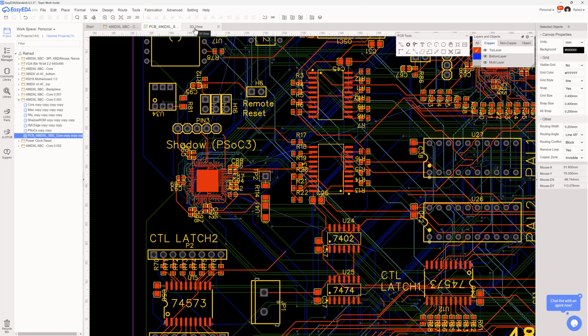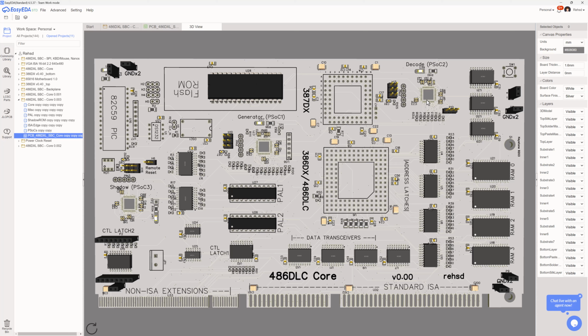So that's a change that I've made: okay, I got the PSOCs on here. I pulled the trace size down slightly just to match the pads on this set of PSOCs. My vias have been shrunken at the same ratio. I'm not expecting any high currents on any of these traces that would exceed the trace size here, but I could be wrong on that.